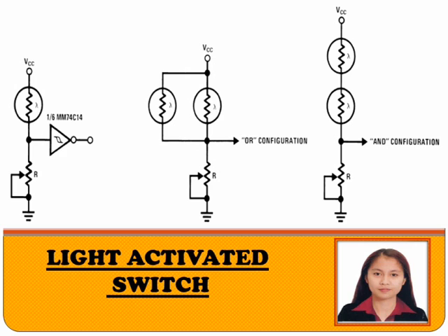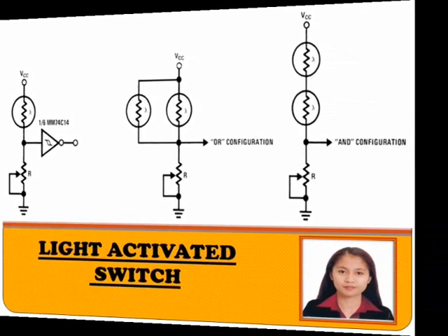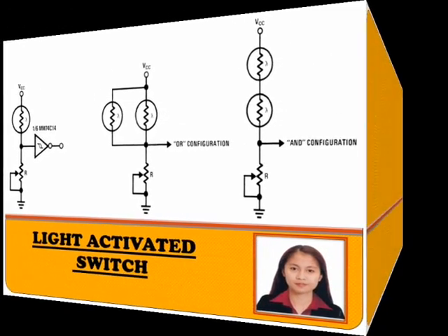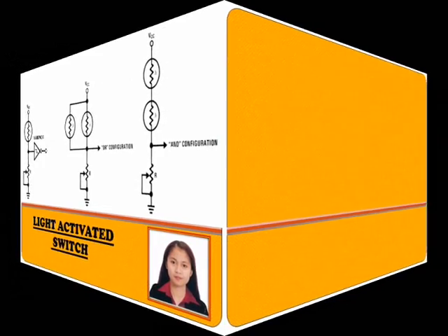The high impedance input of the CMOS-Schmitt trigger makes biasing very easy. Most photocells are several kilohms brightly illuminated and several megohms dark. Since CMOS has 10^12 ohm typical input impedance, no effects are felt on the input when the output voltage changes.